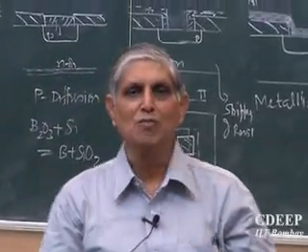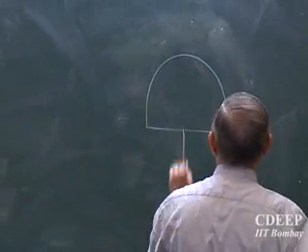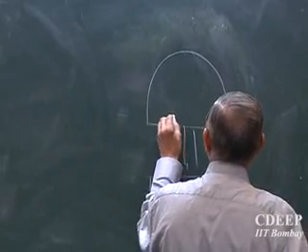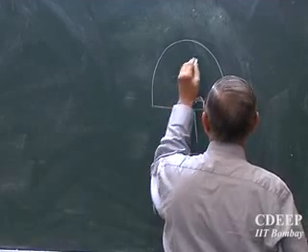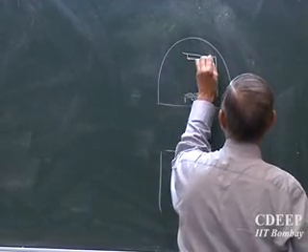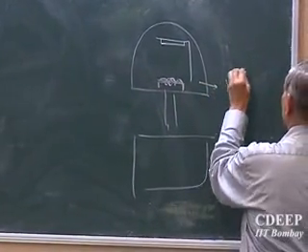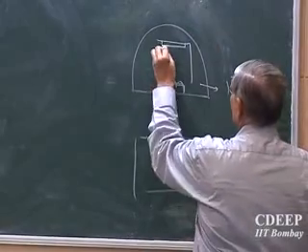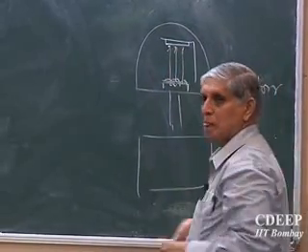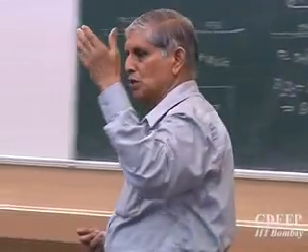In vacuum. So the system built to deposit metals is a vacuum chamber, with a huge pumping system, and we keep our wafers and our source, a tungsten source, aluminium wires. Silicon is held here like this, and if I now heat this in the vacuum, typical vacuum should be 10 to the power minus 6 torr, centimeter of mercury. What is the advantage of vacuum? Can you think? There is no oxygen, for one. 10 to the power minus 6 means very little residual gases, a very small amount.